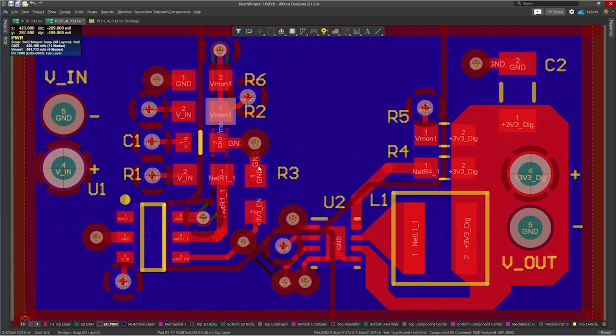It has very low impedance and can source a lot of current or sink a lot of current and provides some capacitive coupling between itself and also the ground plane, which helps with preventing voltage rail collapse.